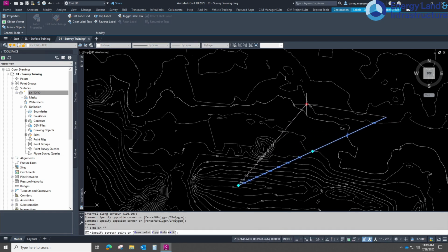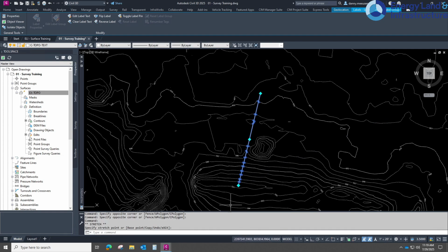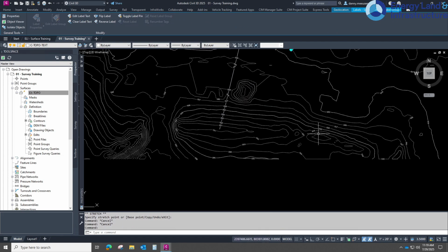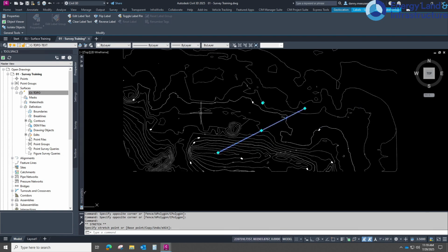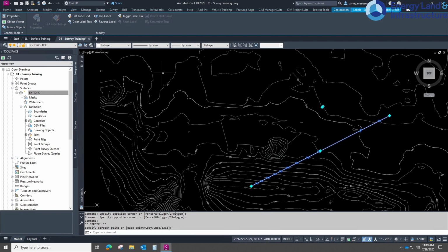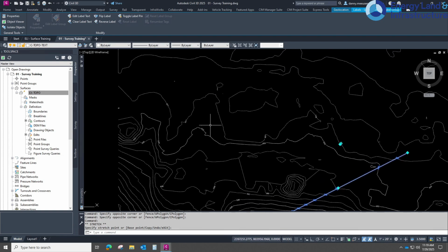Now, if we need to move this around, we can. Let's pull it to here. It's still a multiple contour label, but the difference is it's adding single contour labels every 100 feet. So you need to be careful with this command because it will make a mess very quickly. Where we started with just this multiple contour label line, because we told it to label all of those crossing contours every 100 feet, it's adding single labels to those contours every 100 feet.